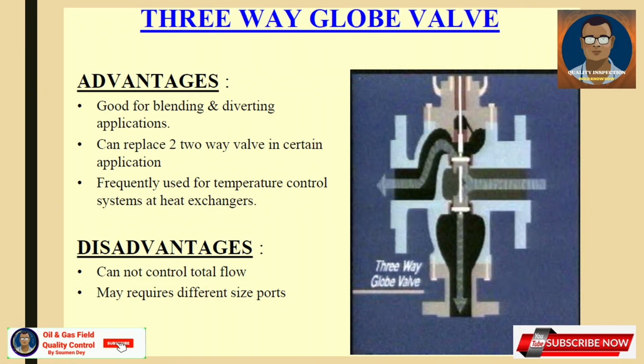Three-way globe valve. Advantages: good for blending and diverting application, can replace two-way valve in certain application. Frequently used for temperature control systems at heat exchangers. Disadvantages: cannot control total flow, may require different size ports.